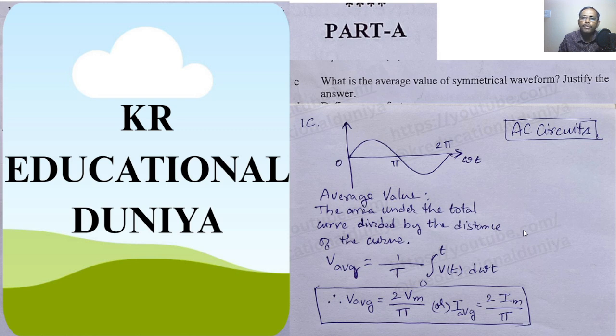You can take any of the waveforms. Here I have taken a sinusoidal waveform. They are asking for the average value of a sinusoidal waveform. Average value equals the area under the total curve divided by the length of the curve. This is the definition. So V average equals 1 by T integral 0 to T V of t d omega t. From this general solution we write V average.